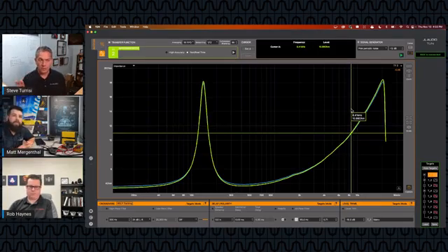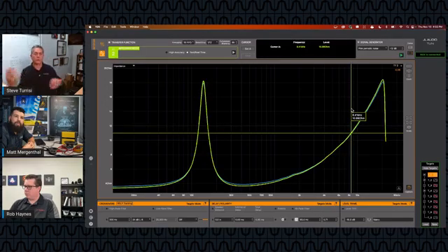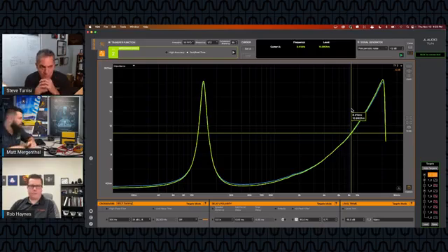And the other two methods allow you to drive the speaker with a separate amplifier entirely, something outside of Max, and simply use the XLR inputs of Max to measure both the voltage and current separately on the outside. Right, you would measure both separately. So the TF1 impedance mode that we turned on earlier, that wouldn't even be used for those setups. Right on. Okay, so it'd be like a transfer function between the voltage and the current on the two XLR inputs. Yeah, exactly. You could do XLR inputs or XLR and RCA and so on.